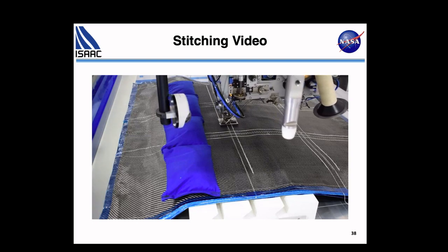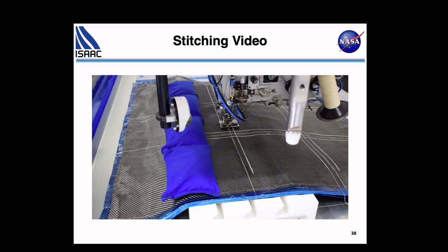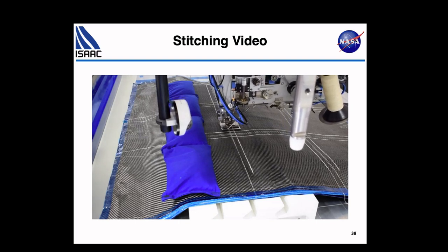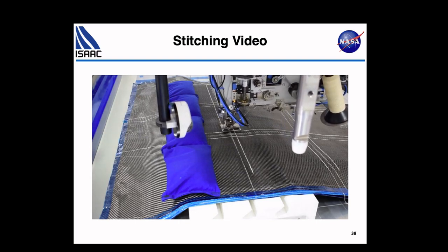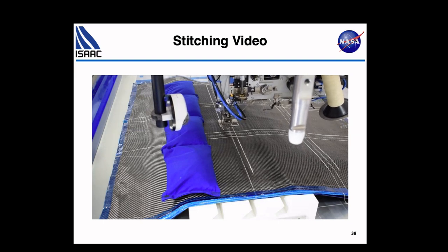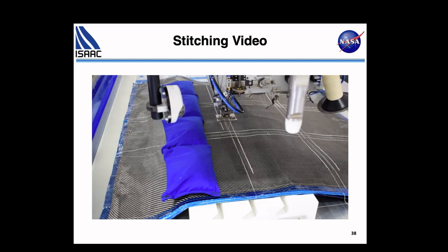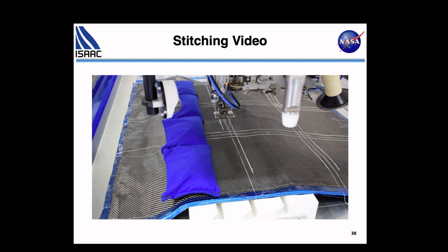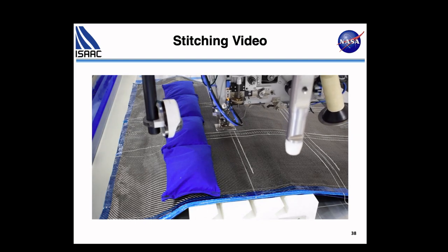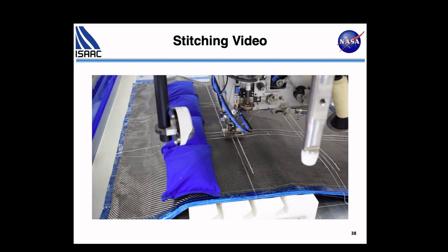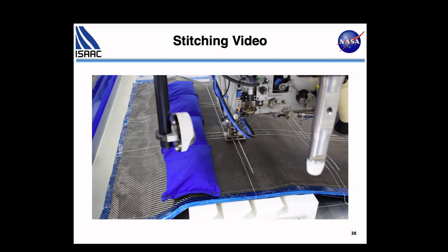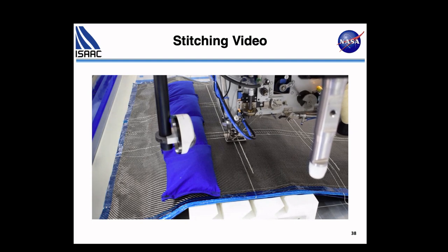Here, if you think about having your skin and the stiffener would be underneath this part. And if you'll notice here, what we'll do is what's just called stiffener jumping, where what we're trying to do is not have to stop stitching, move the robot to the beginning of the next location and go forward, but rather let the thread just spool out enough and then keep going.